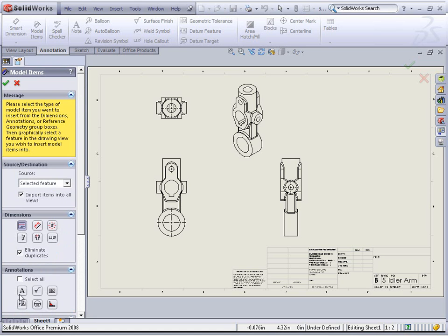So what this area should be telling you is that all these annotations and dimensions should be put in at the model itself. If you do that, not only will your drawings be easier to make, but you'll be ready for ASME Y14.41, which is the ANSI standard that states you don't need a drawing, just the 3D model has all the information to manufacture this part, therefore it's valid.